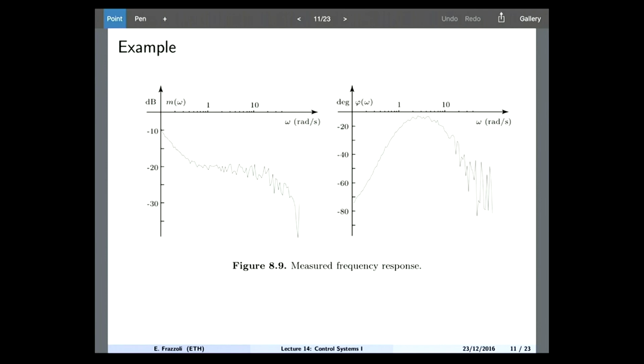And what you can do is, just give a frequency, 0.1 hertz. Apply it, see what happens to your system. Try 1 hertz, try 10 hertz, try 100 hertz. And you will get a bunch of points that allow you to say, at this particular frequency, the amplitude of the output was this much, and the phase of the output was this much.